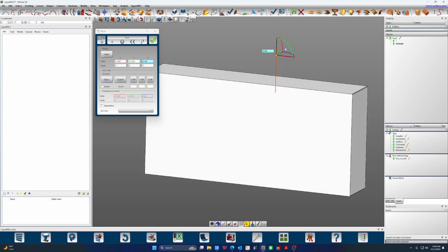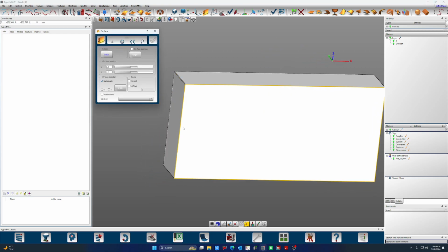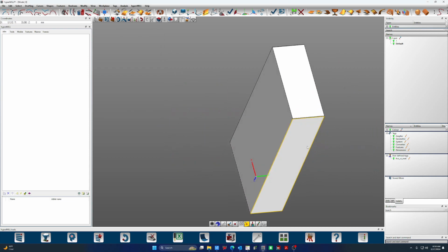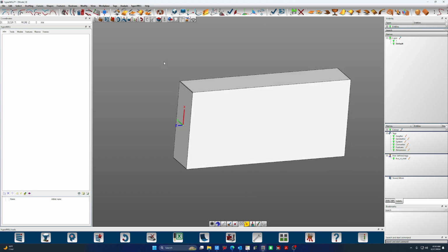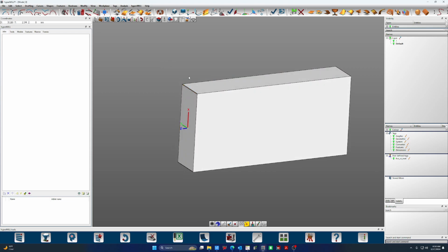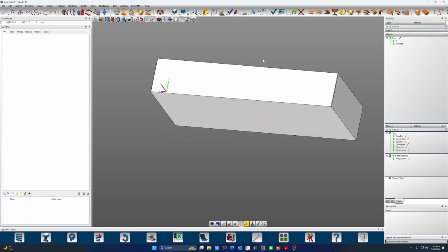And that means to say I can create it anywhere, I can move it around, I can put it on this face, I can put it on that face, I can save workplanes, I can do all these functions with them, and it doesn't mean anything until I tell hyperMILL this workplane is of significance. I turn it into basically the native work plane for a tool path, or I select it to use as the vector for a tilt curve. You can do a ton of cool stuff with it and manipulate it and move it around.